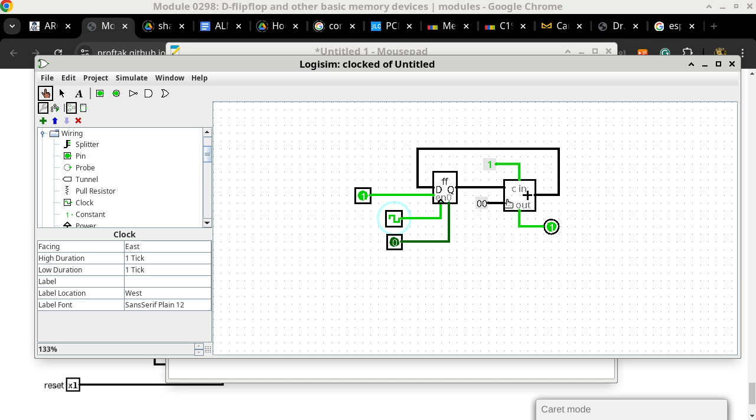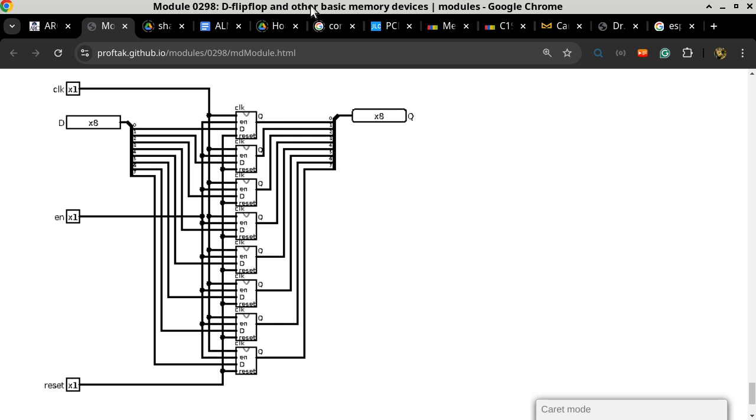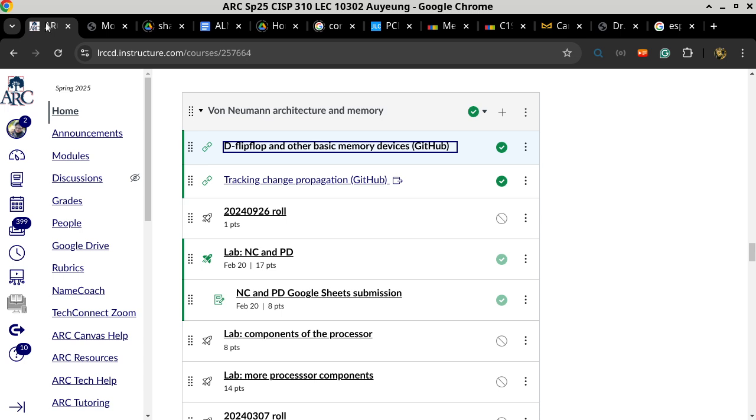Why wouldn't it reach 0? Okay, so you're talking about code outside of the interrupt service routine. To get to the timer, to even talk to the timer, you need to have certain privileges, and your user space programs do not have the privilege to touch any I/O devices. So that's the first hurdle that you have to go through.